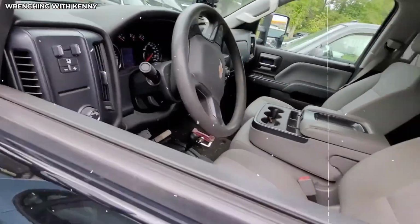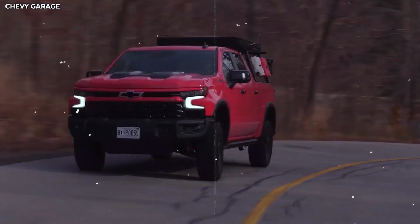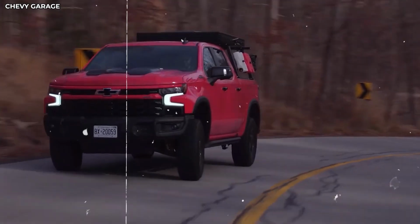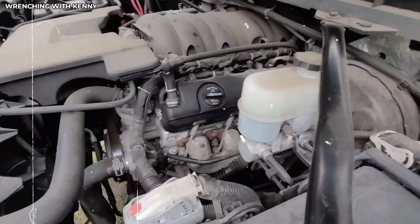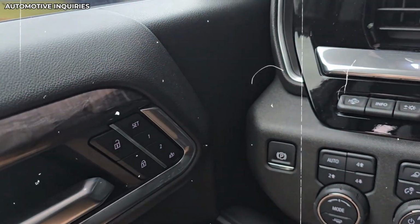If you spend most of your time in stop-and-go traffic driving gently to save fuel, your Ford literally learns to be lazy. The computer starts interpreting every pedal input as a gentle request. It dulls the throttle response curve, shifts the transmission to higher gears earlier, and reduces how much power it delivers at any given pedal position.